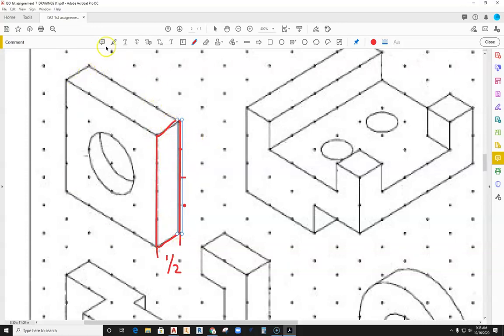Once you sketch out the entire box, then you're going to look at this iso circle. Now, the iso circle will be drawn just like the information given on the object in the video above on how to make iso circles. But you're going to use AutoCAD to create the iso circle. This object is right in the middle of the part because you can look at these dots and see how the dots line up, and that this center dot of the object is here, and that's also the center dot of this iso circle or this ellipse.